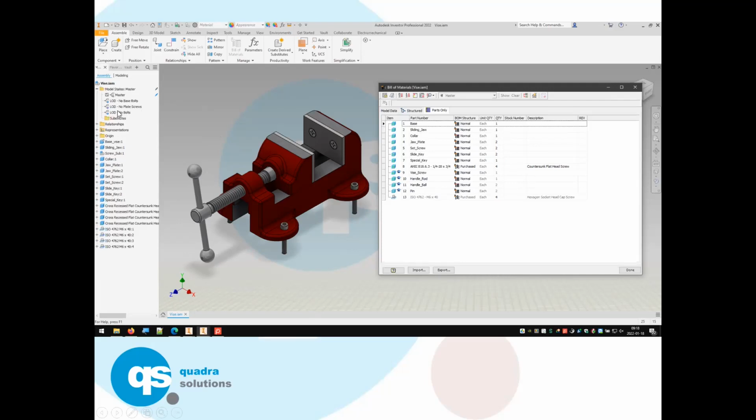In fact, when I was taking this screenshot, I had the no bolts level of detail active, and the act of turning on the bill of materials flicked me over to the master file. So it will always show you the latest information. This is what's known as a delegated BOM. Basically, they are cheating the BOM to make it look like what it did in the level of detail world, so that you've at least got the same information today as what you had yesterday. Rightly or wrongly, the information's there.